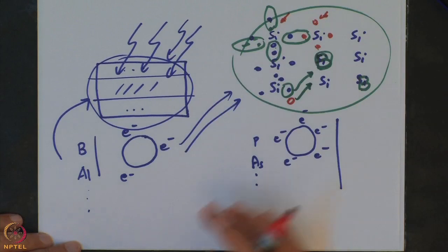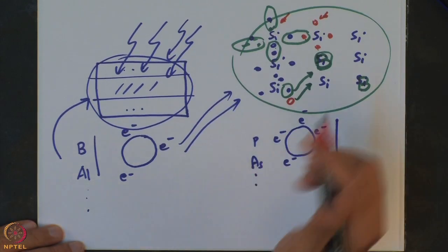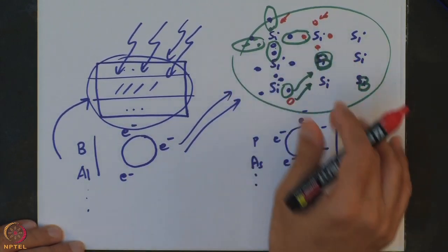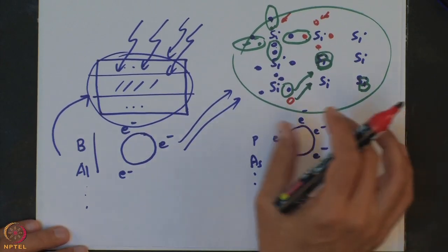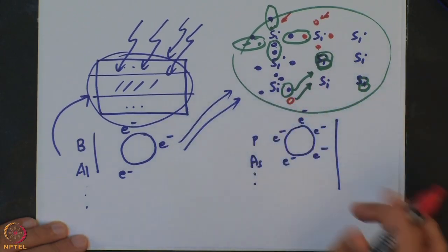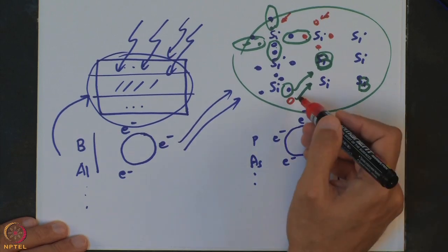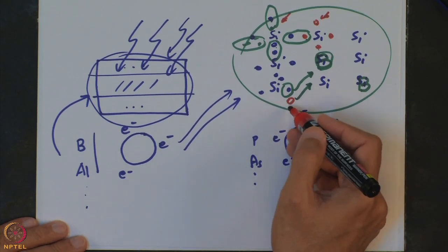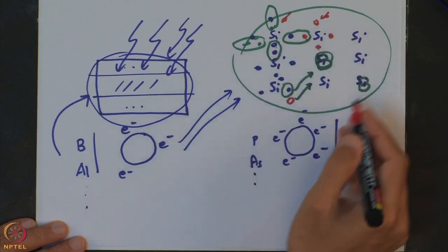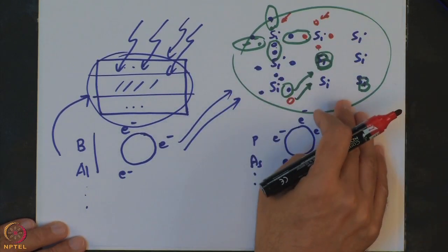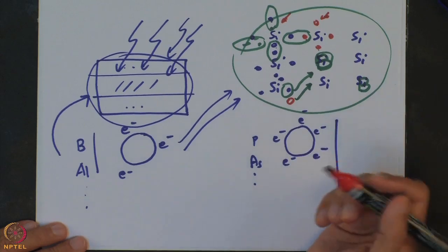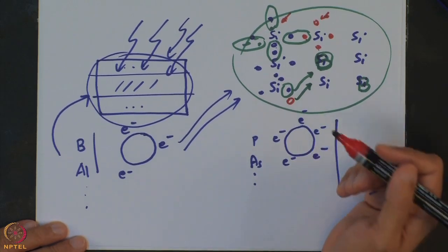So, many of these boron trivalent impurity atoms, when they replace the atoms originally sitting in the intrinsic semiconductor, generate many such missing electron positions or holes in this entire structure. Such atoms like boron are called acceptor atoms or acceptors, or this is called an acceptor type impurity, because it accepts an electron and generates a hole.